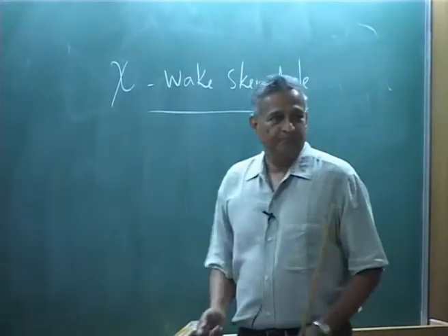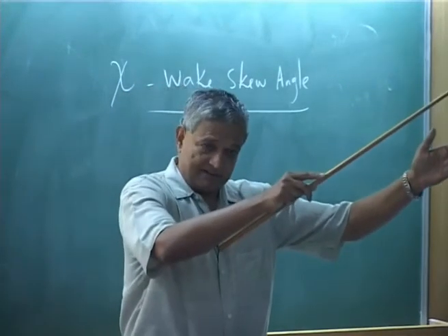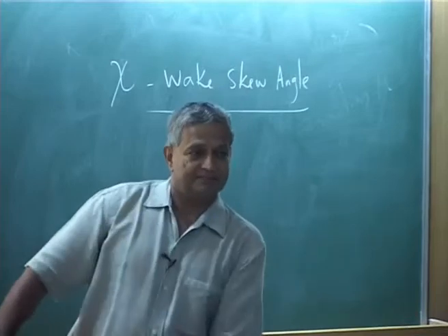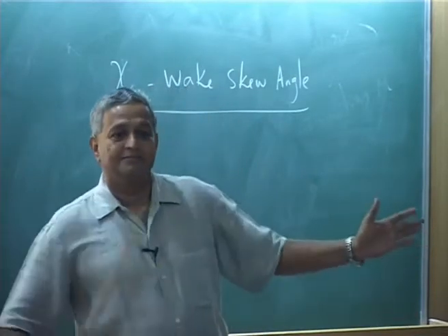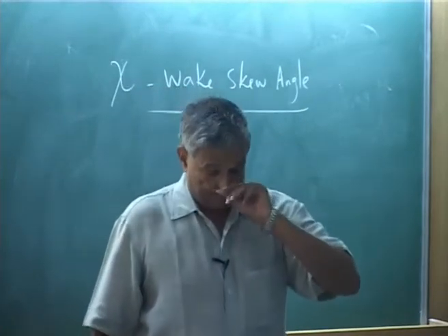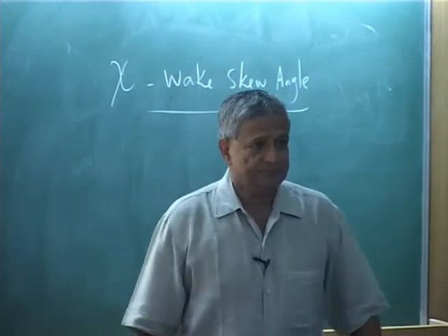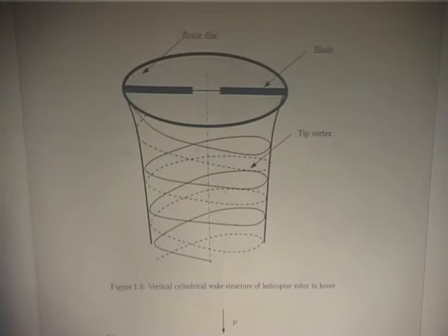Okay. I am taking as though this is a cylinder, skewed cylinder, and on that face I have the vortex. Now, I may use actuator disk theory. Please understand, actuator disk says what? I have infinite number of blades. That means I will have an enormous number of blades, my wake in hover is just a cylinder. Okay.